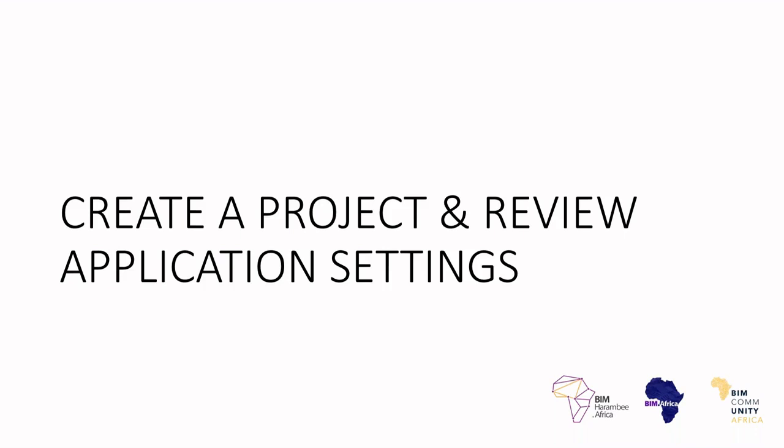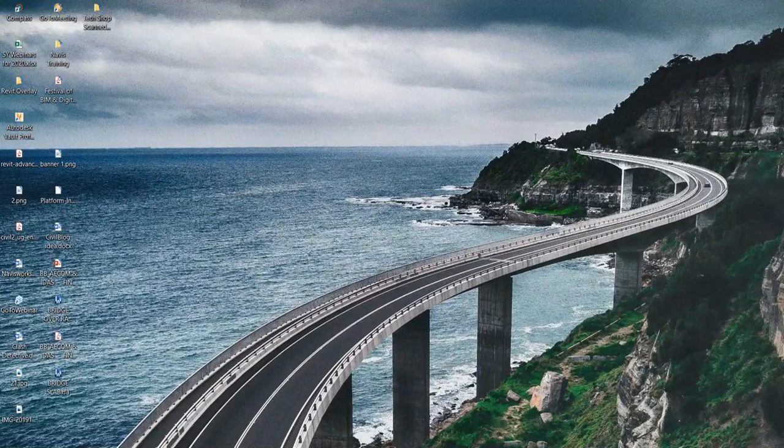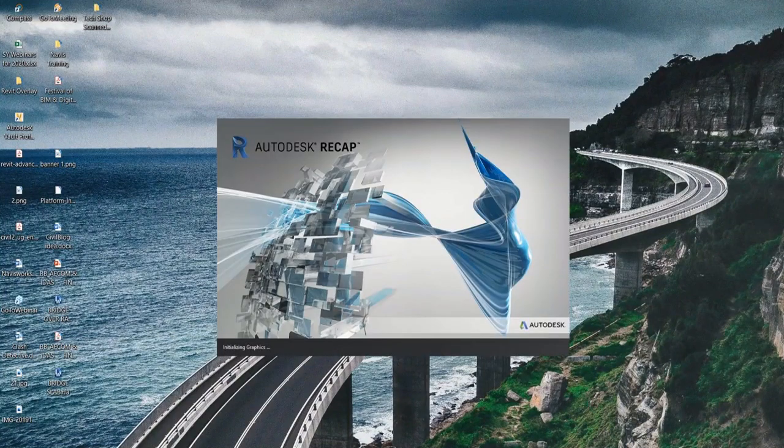Alternatively, if you just open up your Google or your browser and you type in Autodesk ReCap sample files, you will find this TechShop data scan. So if you can get a hold of that, by all means get it, play around with it, and apply what you learned here today. You can always come back and watch the video or this presentation when you are ready. So let's start off with the project settings. So I am going to be firing up Autodesk ReCap Pro here.